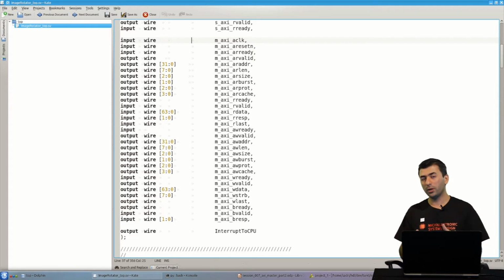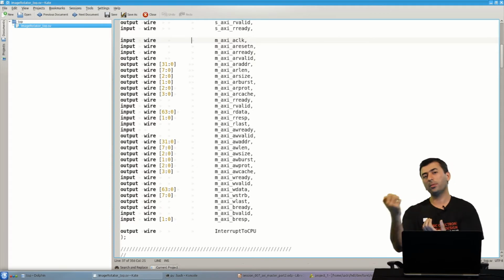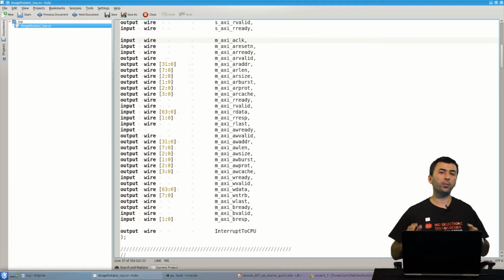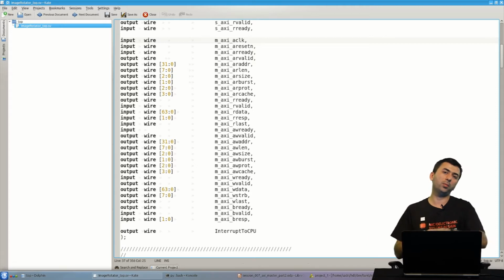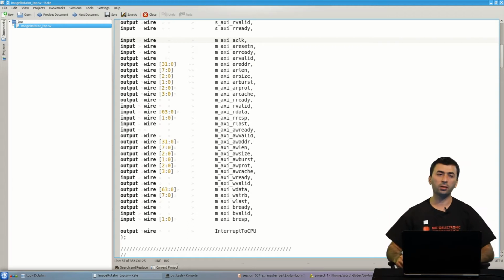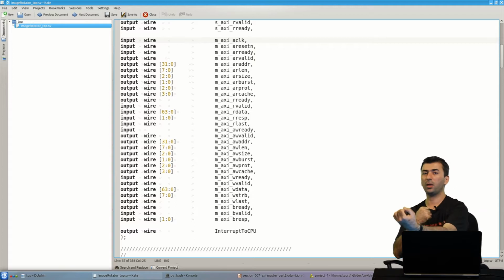Currently what I'm doing in my logic is that I read one block and then I write the result. So as I'm reading this block, I'm not writing any block. I'm only reading this block, and then I begin writing. But imagine we want to perform a copy operation. When I'm copying the image from one location in the memory to another location, I'm probably doing a very simple operation like adding something to each pixel. Then it's not needed that we wait for the read to finish so that we can begin the write. We can have both of them in parallel.